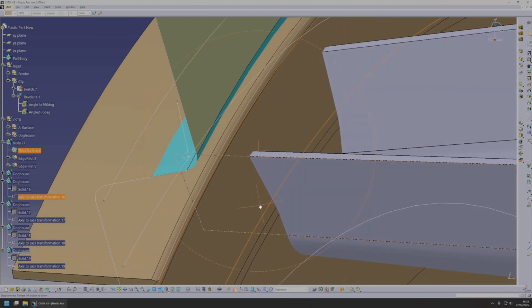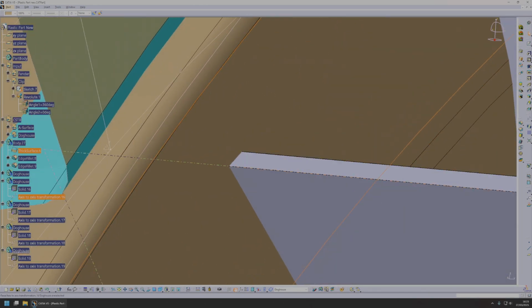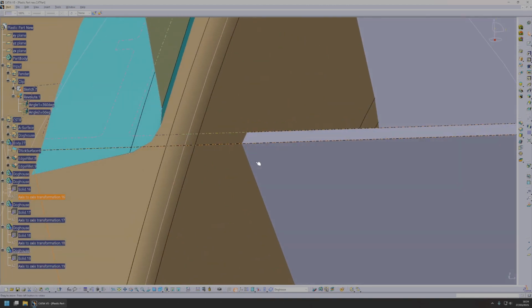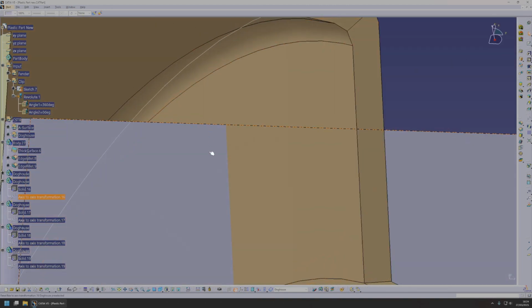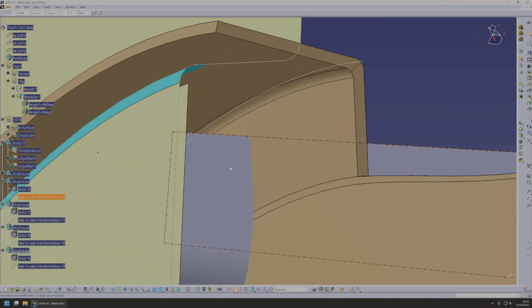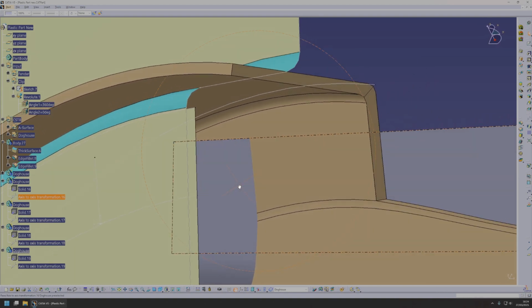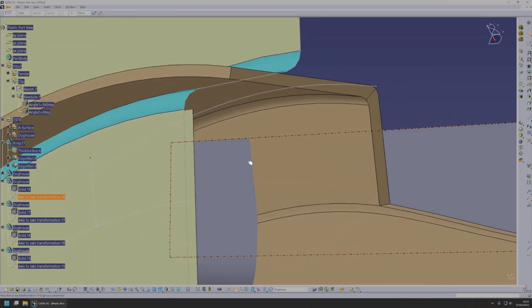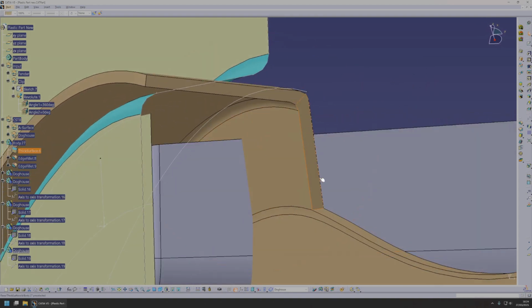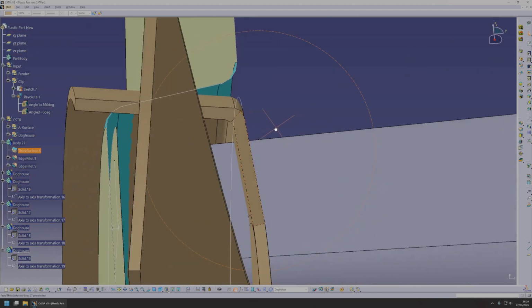And one of the good design ways to avoid this is to have a good ratio between the thickness of the part and the thickness of the wall on the inside, and that is supposed to be no more than 0.75 times the main part thickness.